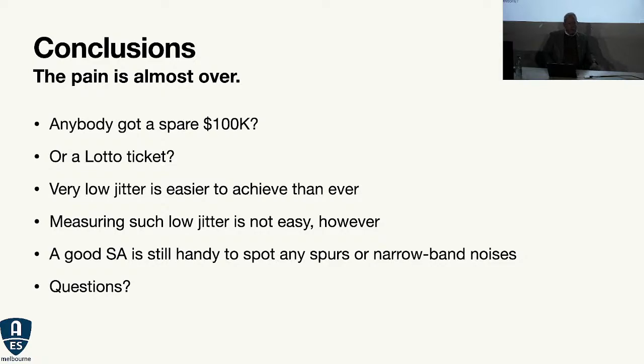Even if you have, say, a distributed word clock that's very low jitter, you have to expect that the devices connected to that word clock are going to be doing the right thing, and that their clock regen is going to be low jitter as well.